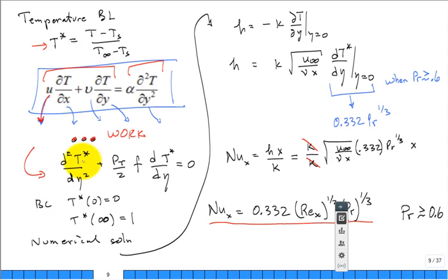Well, look, second order in this dimensionless temperature. Temperature is a function of eta, the similarity variable. We have a Prandtl number, that's just a property, nu over alpha. We have f, that's like the velocity function, the field impact. And then we have the first derivative. So you bring this in from the Blasius solution. There's no way to do this analytically, or somebody probably did, but it's a series solution. You do it numerically.